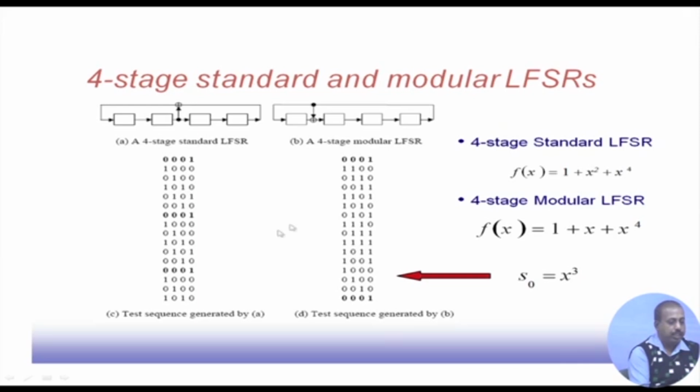On the other hand, if you look at this particular LFSR, it starts with 0001, and if you just follow the logic captured by it, and we are giving clock signals to these flip flops continually, then after initializing with 0001, the value computed at the first cell is this 1 coming back.